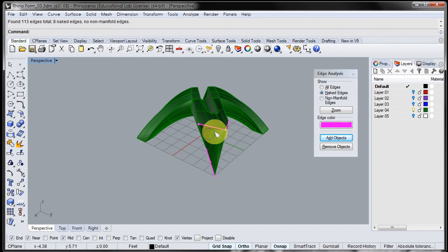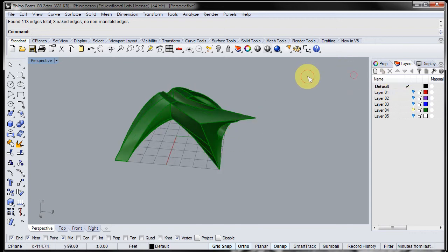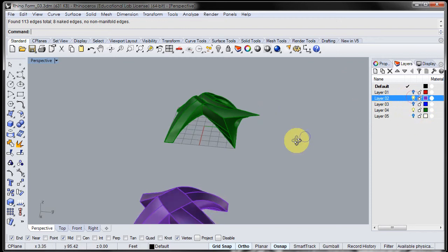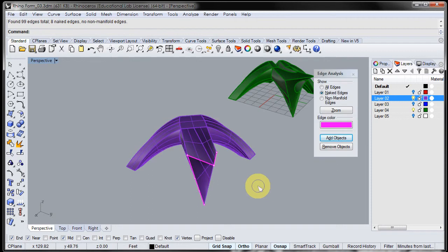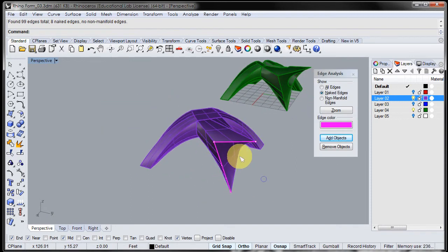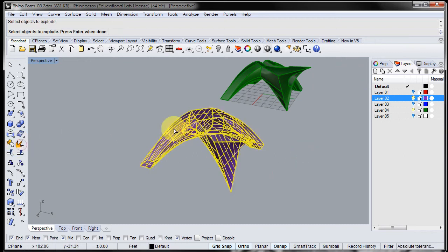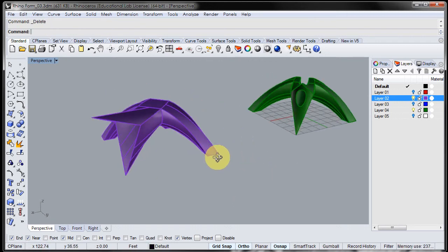And this one is a bit complex because it has this Boolean difference in it, but I tend to save copies of my original solids, so I have a copy over here of that. And if we do a show edges here, right, you get those same edges that are shown, but this one's a bit easier to fix, right, because we don't have this big hole and all that stuff in it. So if I close that, I can explode that one, delete the offending surface, and just go in and redraw that, making sure that my lines are coincident with the edges of that surface.